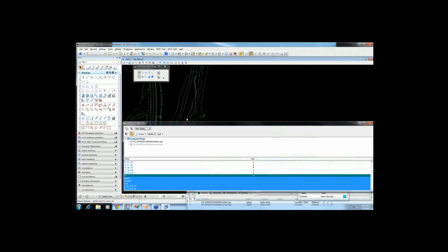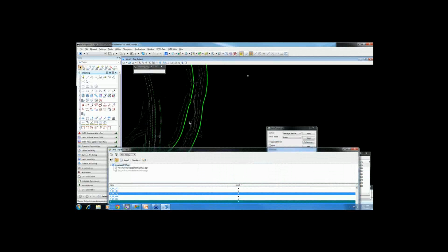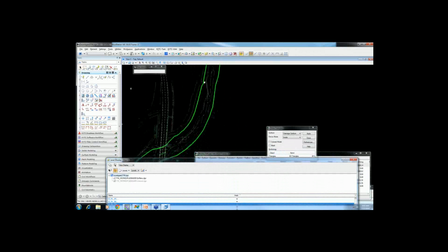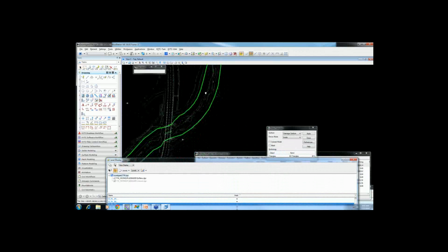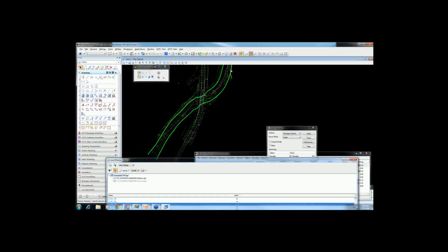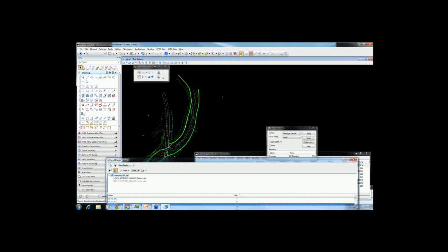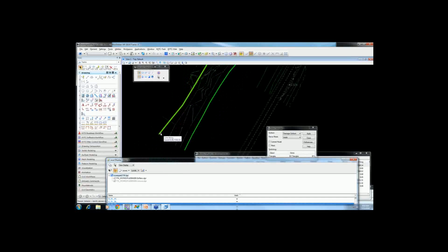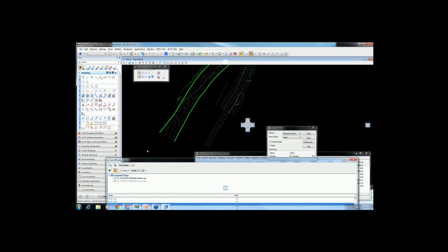This also lets you take some of the kinks out of the lines that might not be quite the direction of flow. So this bright green line is where I've drawn the top of bank. And so I just traced those features that represent the top of bank. And in this project, water's going this way. So I came from downstream to upstream and just traced that. So that's just a graphical element there. And I did the same thing for overbank.